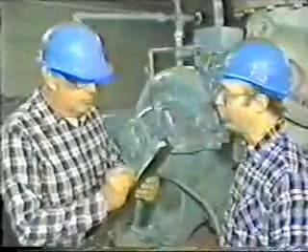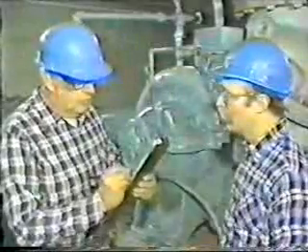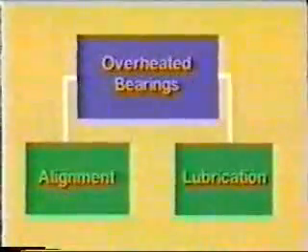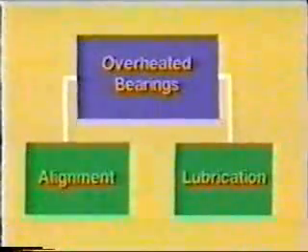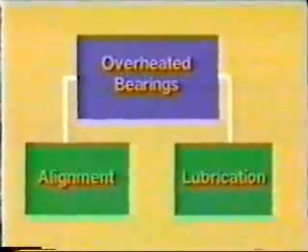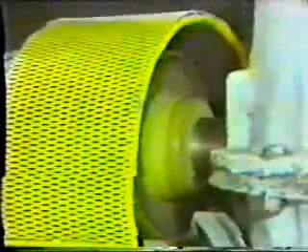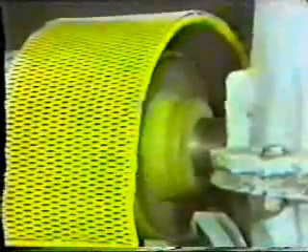During your conversation with the operator, be sure to note everything that could possibly help you solve the problem. For example, Gene learned that the bearings had been greased while the pump was out of service. Gene considers this to be an important piece of information because he knows that bearings must be properly lubricated in order to function. As you know, lubrication reduces friction between moving surfaces. Proper lubrication also helps prevent overheating and wear.